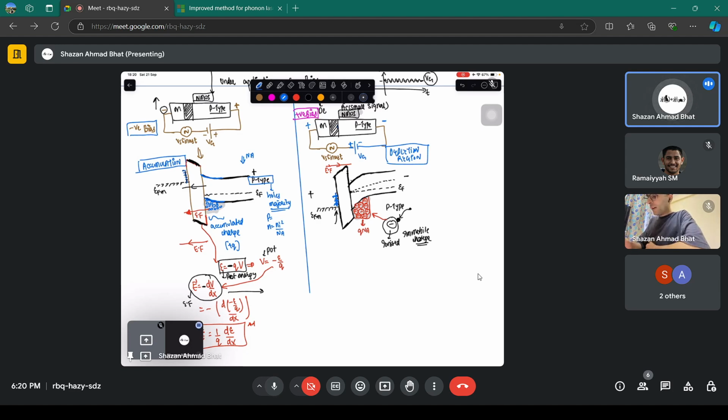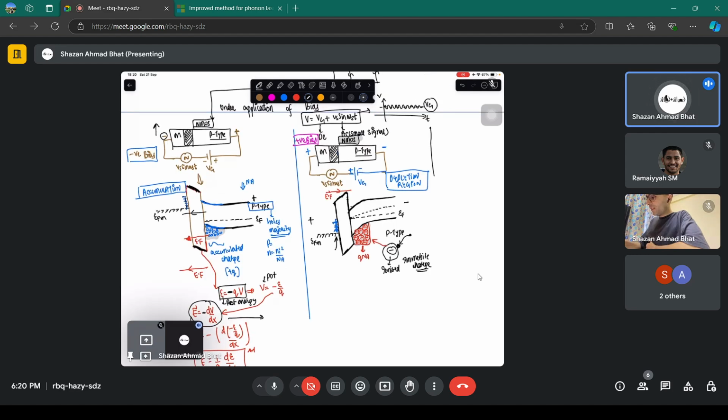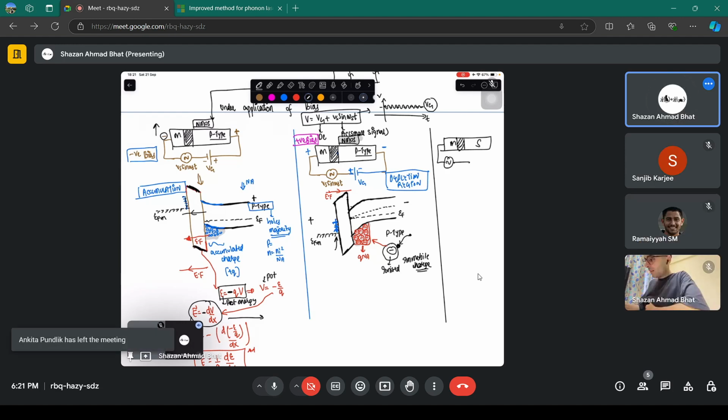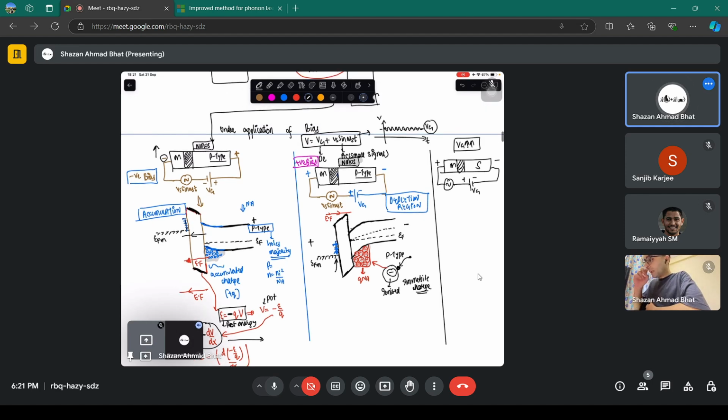We are yet to explain what the voltage range is that we are applying. We are just understanding the regions first of all. Now let's draw another regime. We have this MOS structure. We are now applying the same positive bias, VG, again, but we are increasing VG now more. How much we are increasing is a separate question, and we will discuss it, but we are increasing it beyond something called the threshold voltage.